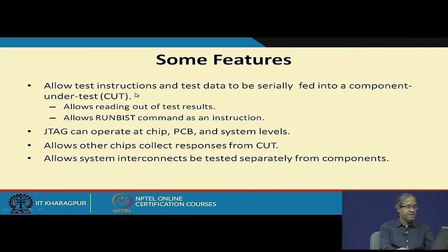So, this standard allows test instruction and data to be serially fed into a particular chip on the board. It also allows reading out of the outputs or the test results. Some of the chips may have a BIST, or built-in self-test mechanism, that we will talk about later, inside. This means the chip can test itself. That can also be included as an instruction.